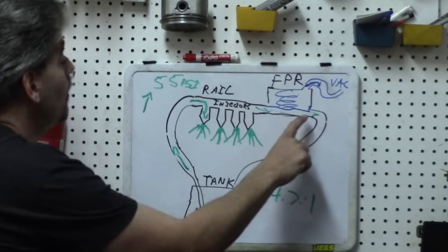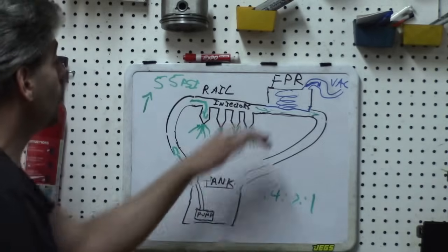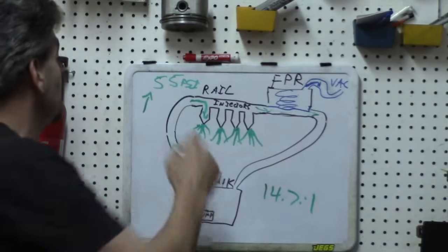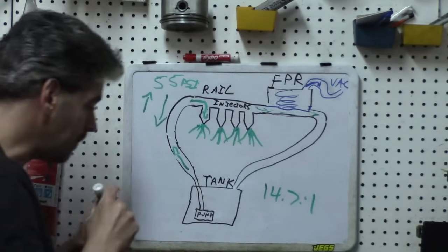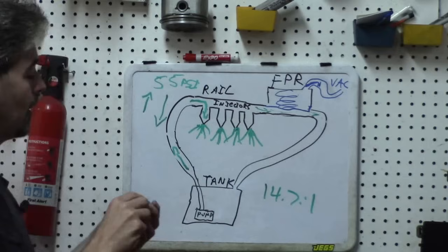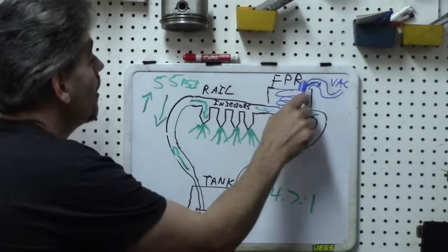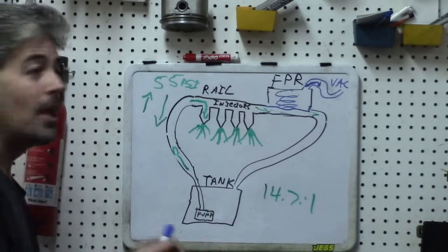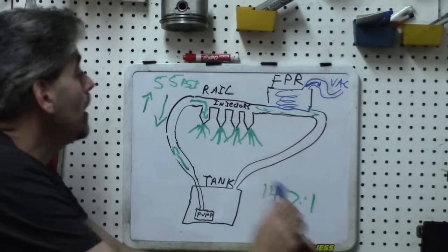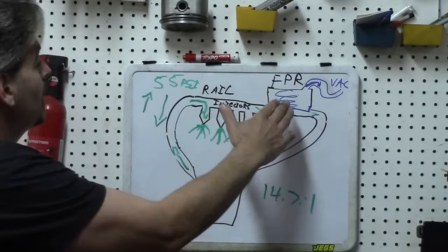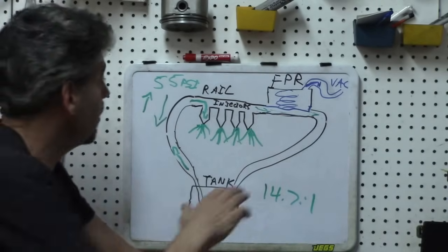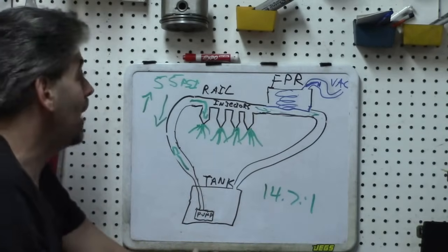What effect would this have on the pressure? Well, of course, by opening this restriction, it would lower pressure to the rail. Now, the important thing to understand is that alone right there kind of tells you what you would do to diagnose this fuel pressure regulator. So before we explain how this works with the injector pulse length, let's think about this for a second.